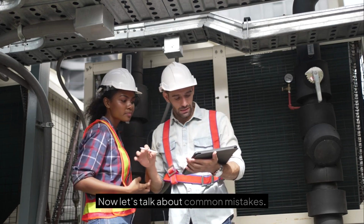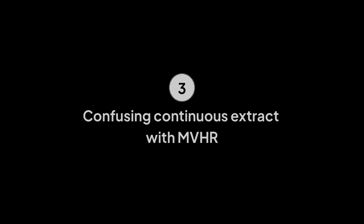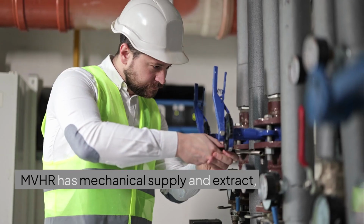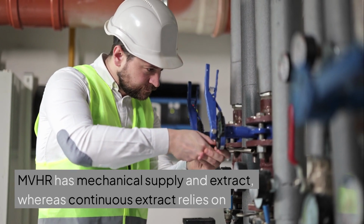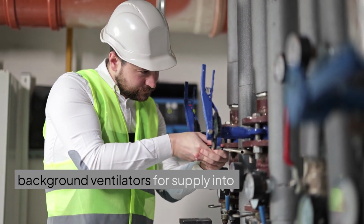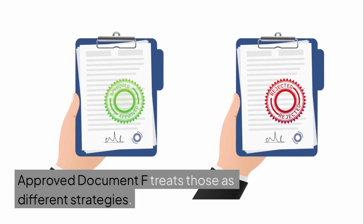Now let's talk about common mistakes. Mistake number 1 is remembering the high wet room rates, but forgetting the whole dwelling continuous total. Mistake number 2 is putting background ventilators in wet rooms when the guidance says they should not be there for this system type. Mistake number 3 is thinking continuous extract is the same thing as MVHR. It is not. MVHR has mechanical supply and extract, whereas continuous extract relies on background ventilators for supply into habitable rooms. Approved Document F treats those as different strategies.